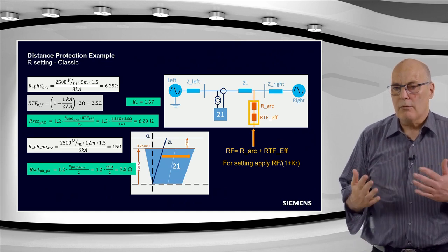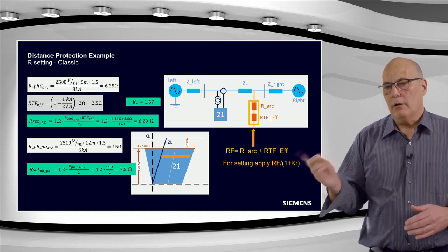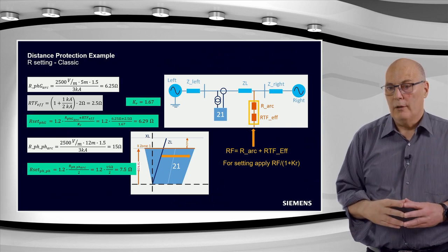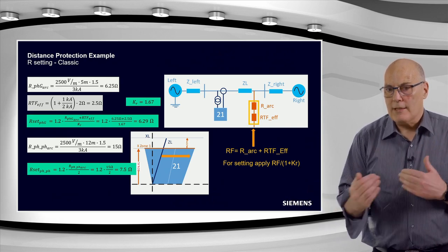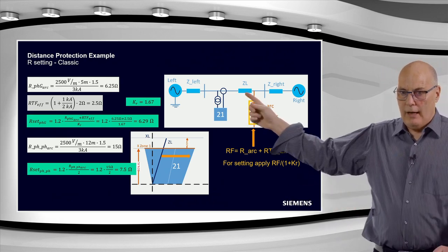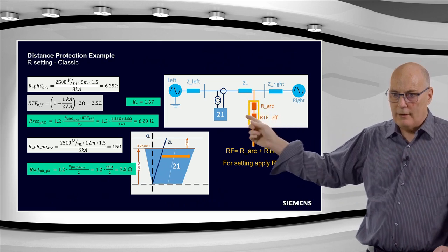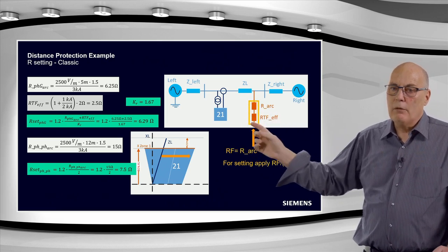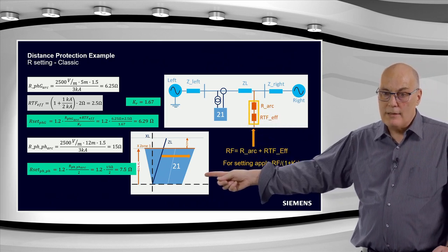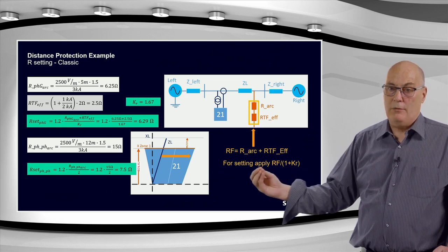It is because the equation that we're using to calculate the ground resistance, as shown early on with those factors, extracts the positive sequence impedance. Remember, the loop current will be the ZL out and the ZE return, but measured and applied in this curve here is only the positive sequence impedance.